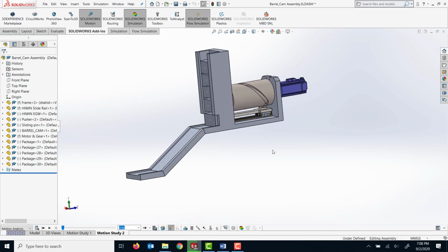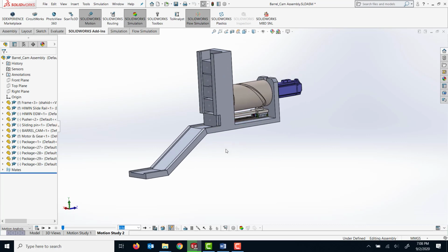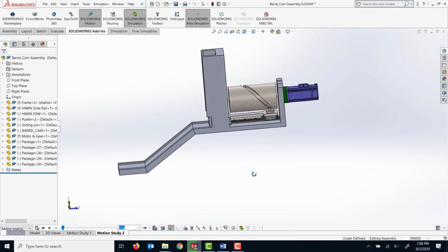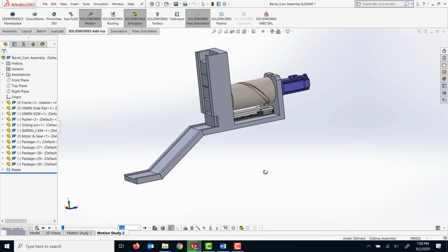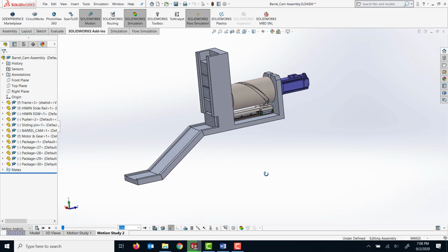In this lab exercise, we are using a barrel cam actuator and we are transferring some of the packages. We are pushing it down using this pusher down this ramp. And the barrel cam is run by this motor. Barrel cams are very common in the industry. They're used for sequential motions as well as indexing and so on and so forth. And a barrel cam could be used to control two or multiple mechanisms.